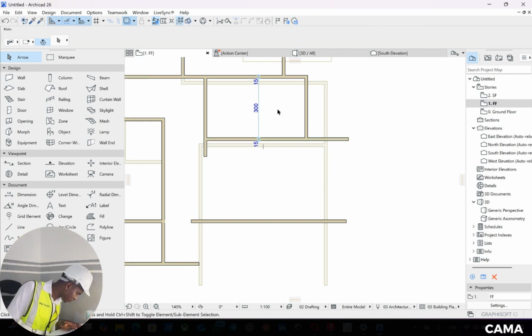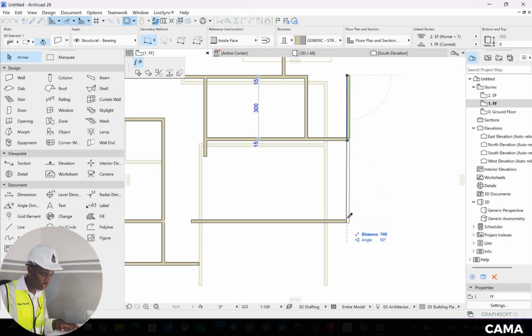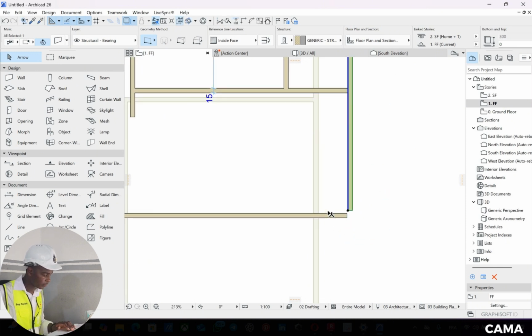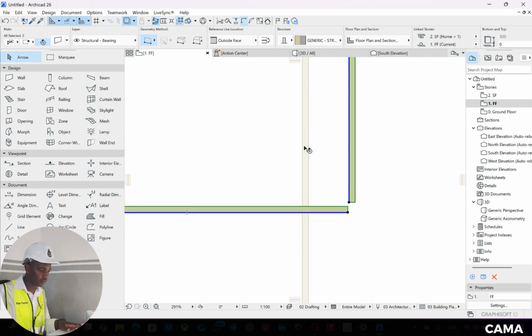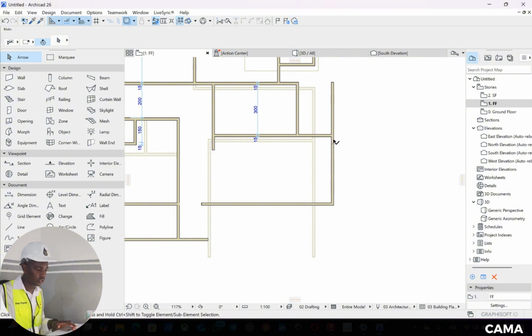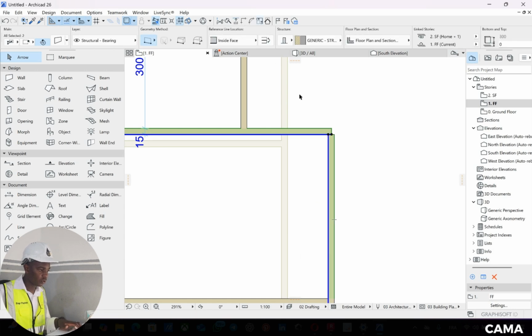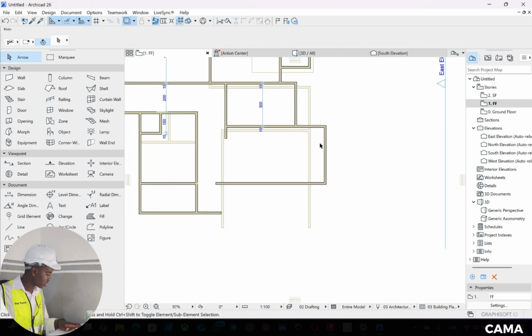Then we see that this wall, if we duplicate it at this distance, 215, we press enter and we extend it here. We are going to have a balcony. Select, join like this. You can come later on and delete this wall because it's of no use. Select, you intersect. So that's the space for a balcony. We still need to reduce it.